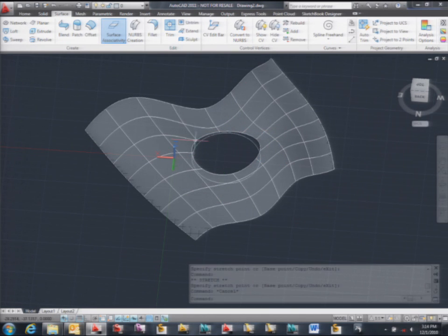If you want to untrim this, either you select untrim because you still want to keep the geometry there, or you basically delete the circle, and of course, since there's no circle, there's no trim because everything is associative. So depending, if you want to keep the circle for another thing, just do untrim, and if you don't care about the circle, just remove it and you're done.